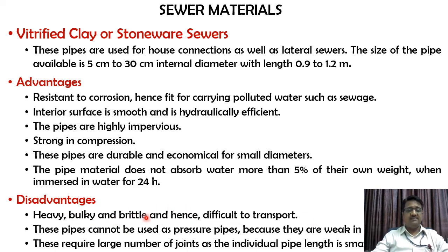So the only difficulty over here is, even though in advantages we have mentioned it as strong in compression, it is not strong in tensile forces. So it is basically a brittle material. If you put a uniformly distributed load, it will take it up. But if a point load is added, and that too at a rapid pace, at that point of time it is going to get cracked. So that's why it is brittle, and hence it is difficult to transport.